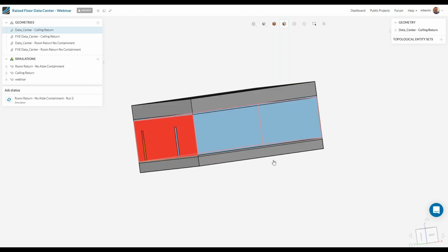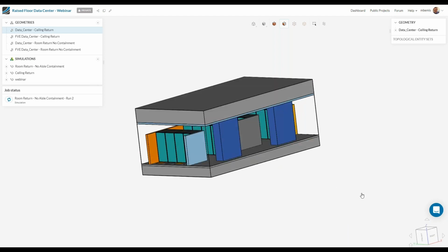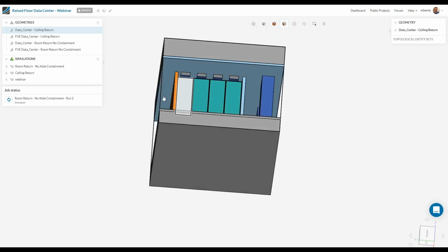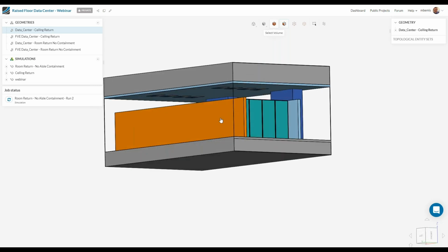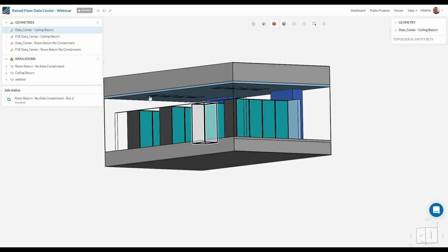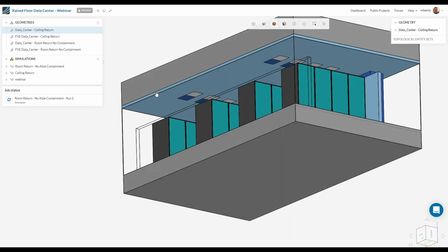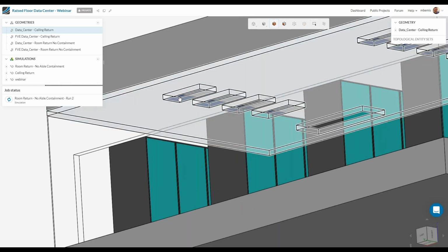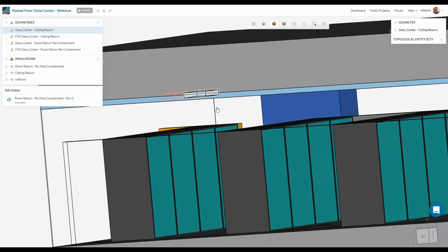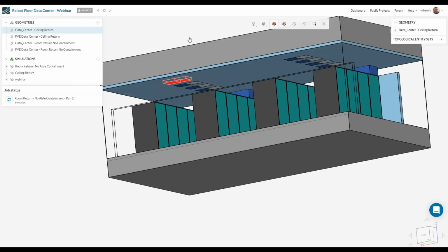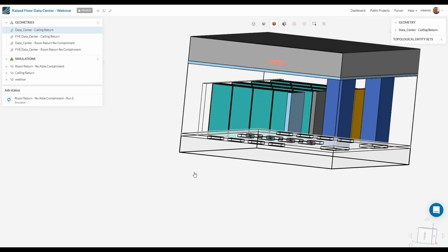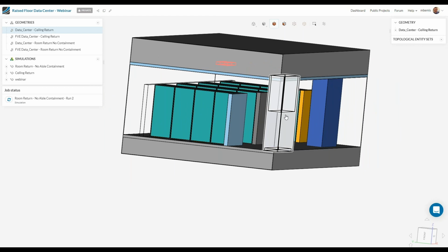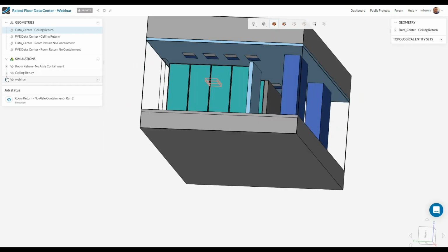So I think if you understand one, you'll understand both. And I guess the primary addition is now the ceiling actually kind of looks like the floor as well, right? We've got these tiles up here. The hot aisle has the airflow go up into the ceiling plenum, and then the CRAC units are ducted to the top. And so let's jump into results.